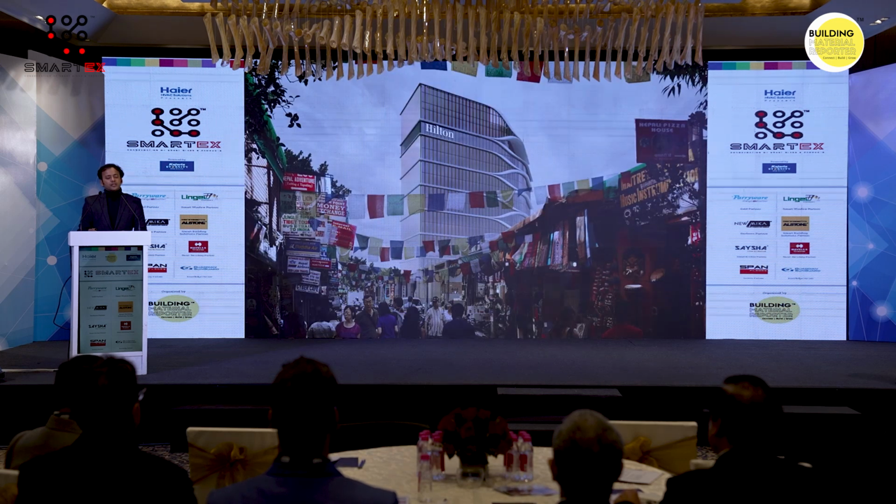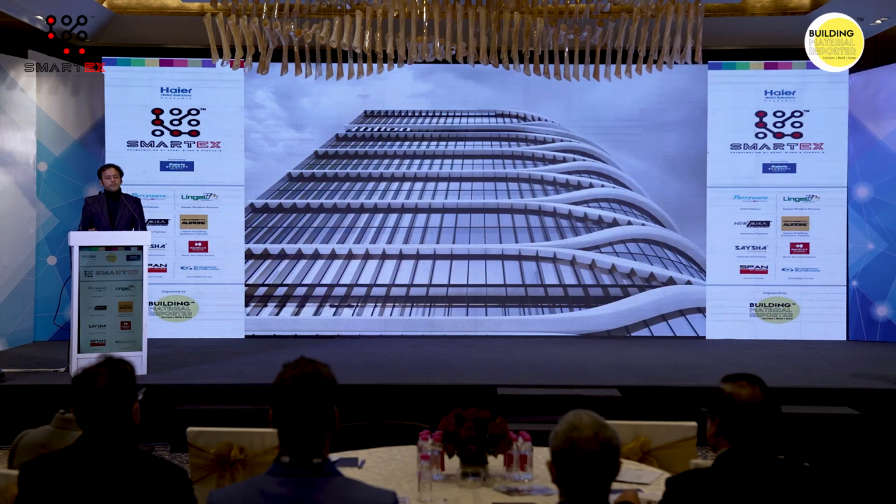So dichroic glass, around 6 years ago when we started using this, we had shortlisted a couple of things. Schott glass was one, but then costing becomes a very big aspect in any architectural project. That was costing around 300 euros a square foot, which was not possible. So we came up with a dichroic glass, which is a laminated glass with a dichroic film in between.